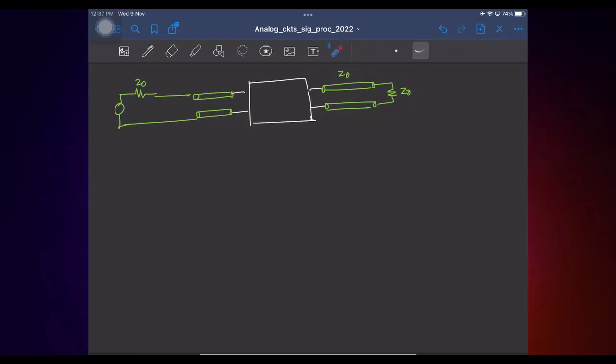No. I'm not trying to see. This is only for characterizing this network, right? The whole idea started because he wanted to characterize this 2-port network. He wanted to measure some 2-port parameters for this, right? So the network is floating. So the input impedance is not 0 as we wanted it to. We wanted a short. Exactly. So let's come to that. A variable load that varies with the frequency, so that it always looks like a short. Yeah, that is not possible, unfortunately.